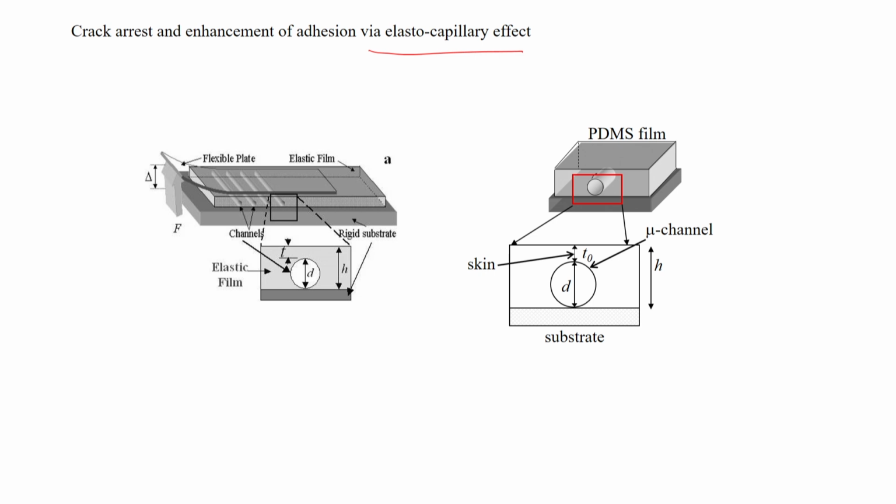So for example, if this interfacial energy decreases, let us say over here you have put a liquid. As a result, this surface likes this liquid. So there is wetting over here, meaning this surface is wettable by this liquid. Then the interfacial energy will decrease, and if the interfacial energy decreases, it has some excess surface energy available. In other words, because of the change in the interfacial tension over here, this curvature can increase. As a result, there is a deformation, and this thin film deforms over here like that.